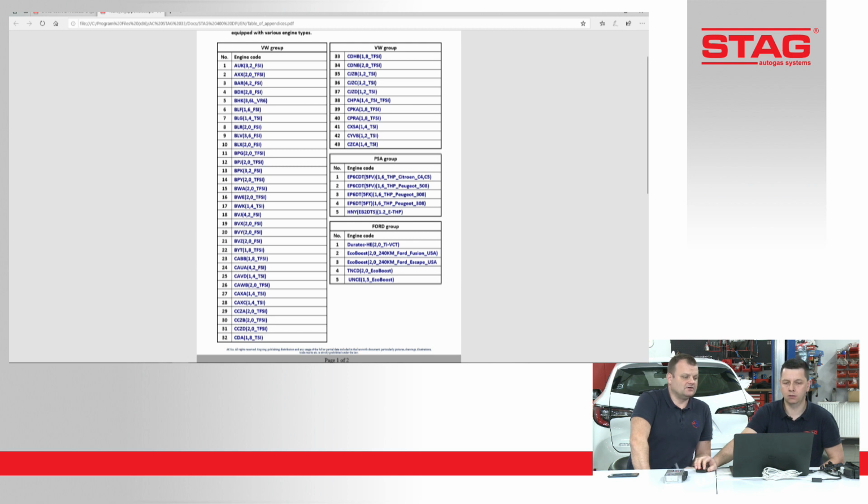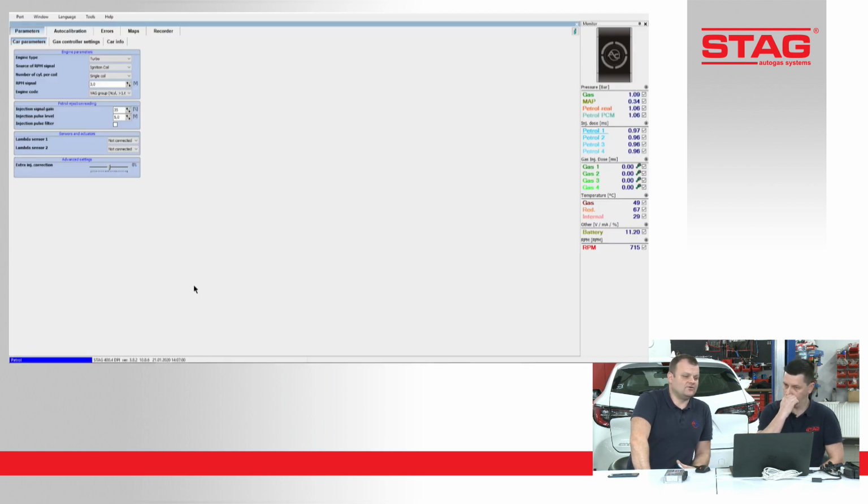If you are installing the system, compared to other installations, the electrical connections are very similar, just with an additional pressure sensor. The installation of the injectors compared to the MPI engines is also very similar. So from the point of view of installation, the step-by-step rules are very similar to MPI. The only main difference is that you need to follow the pinout strictly.